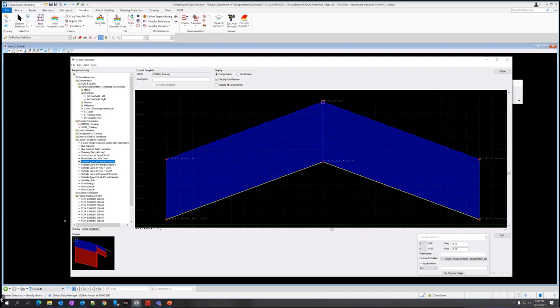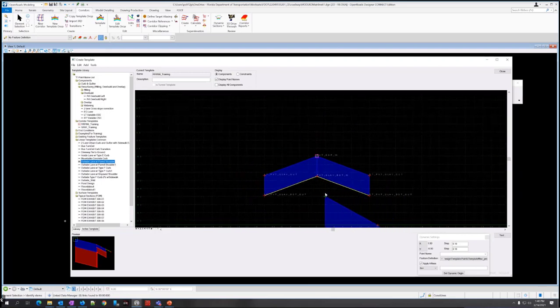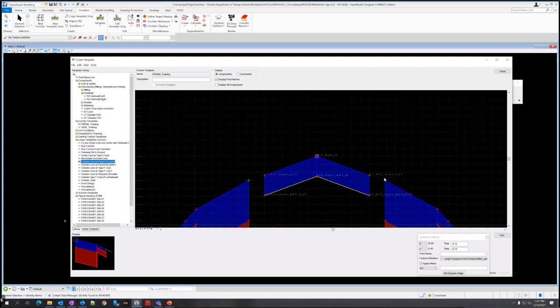So, take this slow. What you want to do is start dragging it. Don't let go of it yet. Right click. Now once you right click, then you can let go of the left mouse button. It's not going to do anything yet. Then you do mirror. So check that from the menu.